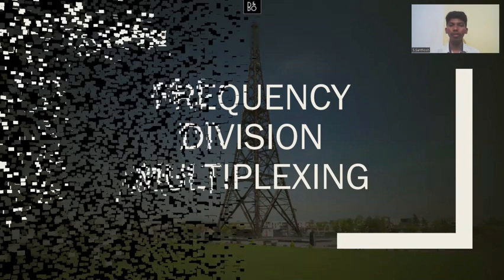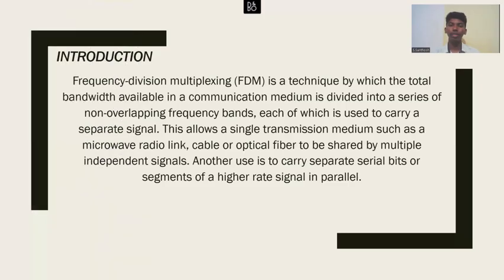This method is actually a very efficient method when compared to other multiplexing methods like TDM and STDM, which stand for time division multiplexing and statistical time division multiplexing, where those two methods only allow one message to be transferred at a time. But in frequency division multiplexing, we can have n number of messages transferred from one place to another at a time. Many channels can be used for communication, whereas in the other methods you can only have one channel where the communication has to be done.